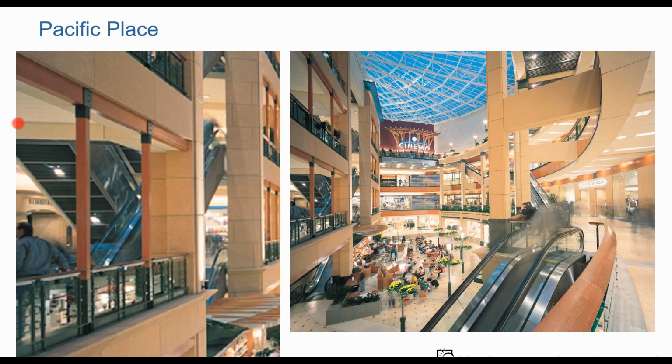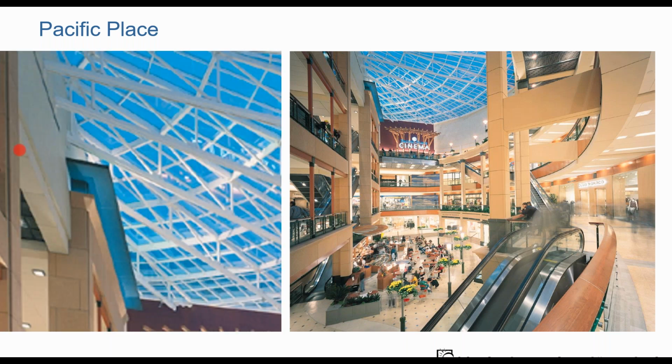So a very similar kind of thing with respect to this was the parapet lighting. So we have neon in this parapet up here. You can see kind of the blue. And we also have a variety of ceramic metal halide accent lights shooting across the trusswork. The idea here is that this emulates some lighting that's over here that catches from uplights from below. And this, of course, is meant to keep that whole trusswork from appearing dark and ponderous at night.